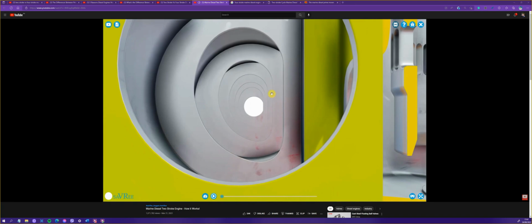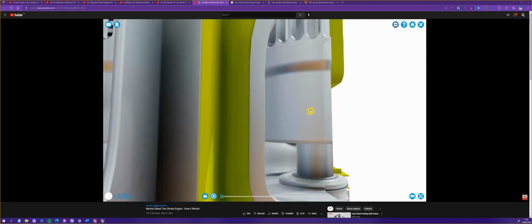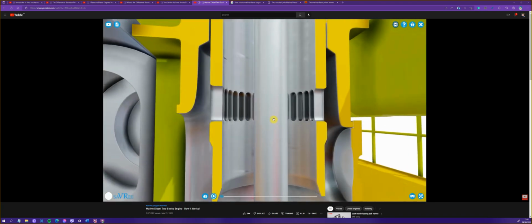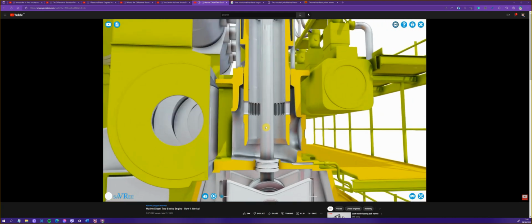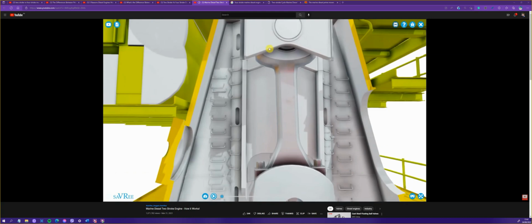We call it charged air because it's passed through the turbocharger, and this charge air will then be fed into our combustion space, or our combustion cylinder. So it will come from this direction here, and it will actually travel up and straight in to the combustion space. So we're inside the combustion space, or the cylinder, and we've got this long piece of cylindrical steel, which is inside our combustion space as well. That is our piston rod. Below the piston rod, we have a connecting rod.